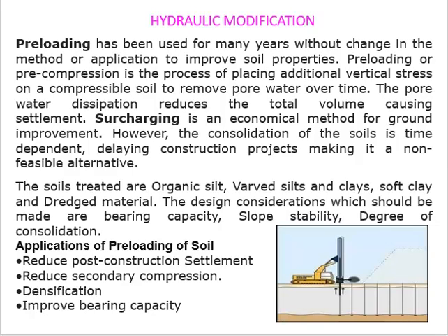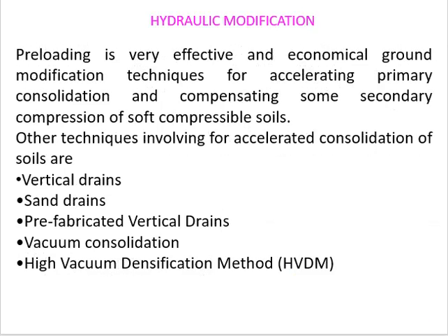So the applications of preloading of soil is to reduce post-construction settlement, to reduce secondary compression for densification, and to improve the bearing capacity. Preloading is a very effective and economical ground modification technique for accelerating primary consolidation and compensating some secondary compression of soft compressible soils.